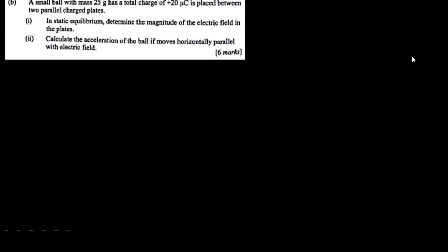Now, the next question is going to be on capacitors. Right. So let's read the question. An uncharged capacitor of 58 microfarads is connected in series with a resistor of 100 kilo ohm. Okay. So once I've read the first sentence, I can immediately start my calculation actually. So I can immediately calculate, because we know this about capacitors, the value for RC. So C is going to be 58 times 10 to the power of negative 6, right?